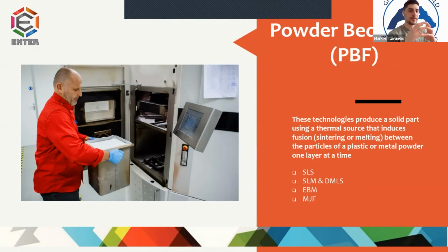All powder bed fusion processes involve the spreading of the powder material over previous layers. A hopper or a reservoir below or aside the bed provides fresh material supply, and then the laser beam goes on top of each point, melting it and creating the solid metal.